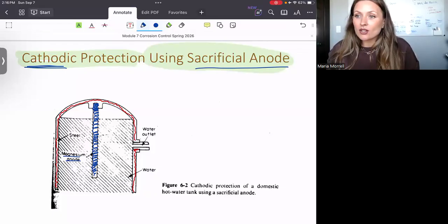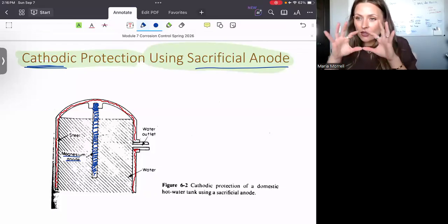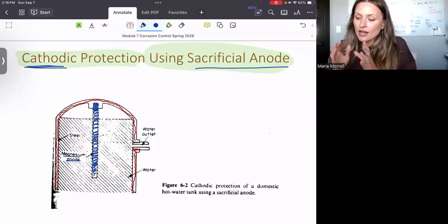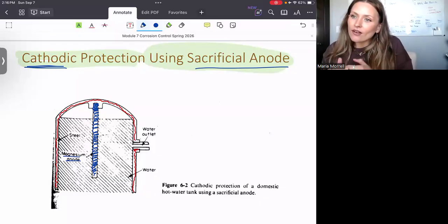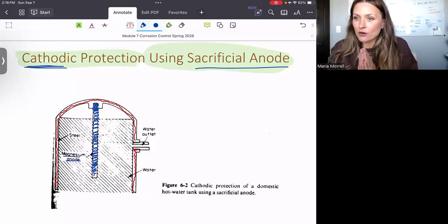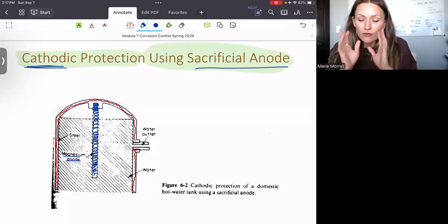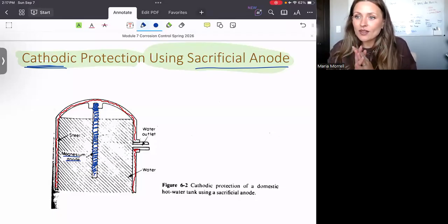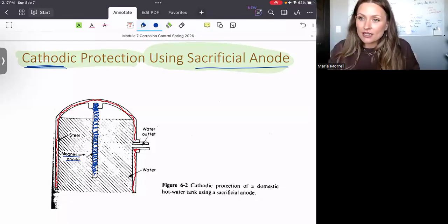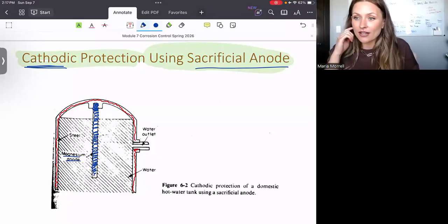So what's going to happen is that you are guaranteed to protect, let's say, up to 5 years, but they will never sell you insurance for longer than whatever they know they have it protected for. Let's say if they know that this magnesium anode will only last for 5 years, that's the only insurance that they will give you. They will give you 5 years and not more than 1 day. Because beyond that point, once the magnesium anode is gone, once it disintegrated, once it got sacrificed, the next thing to get corroded is your tank. And that's why nobody's going to insure anything like that.